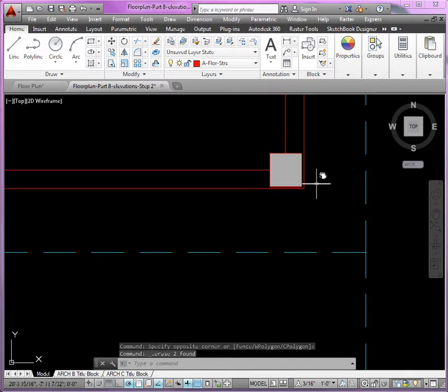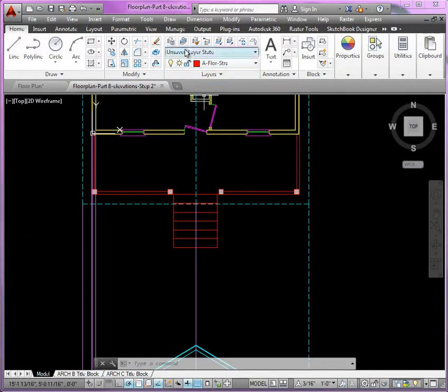Now we have to show where these posts are. This is going to be the posts that hold up the cantilevered roof there, as well as the beam above, but to which the railings will be attached. So what you'll want to do here is show the columns. Let's make the construction line layer current. And you can see there's the 4 columns. Let's just work with this half.